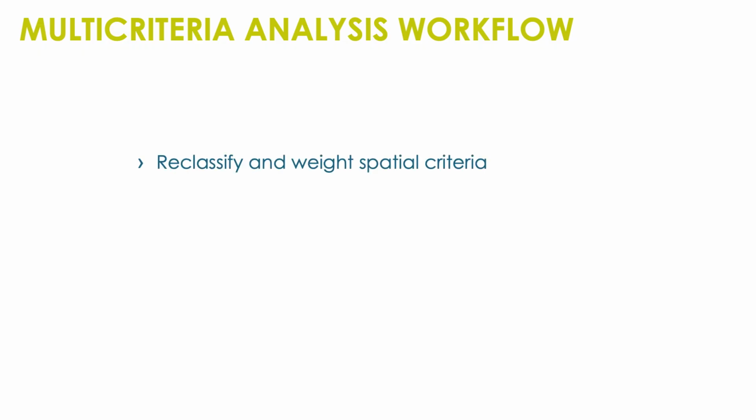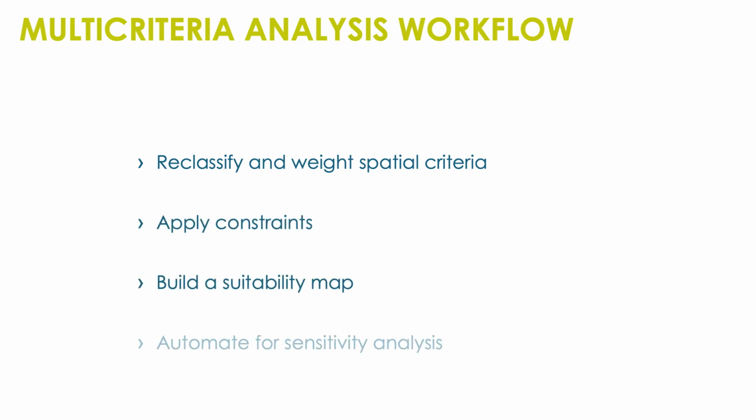Great! You've now seen a full multi-criteria analysis workflow. You've seen how to reclassify and weight spatial criteria, how to apply constraints, how to build a suitability map, and how to automate the process and make it suitable for sensitivity analysis and validation. This is a core skill in geospatial energy planning.